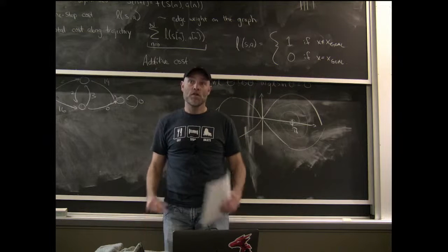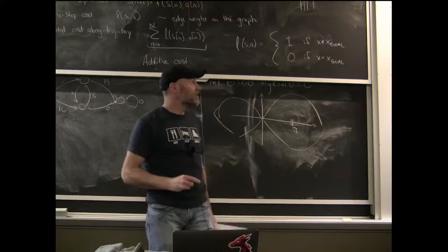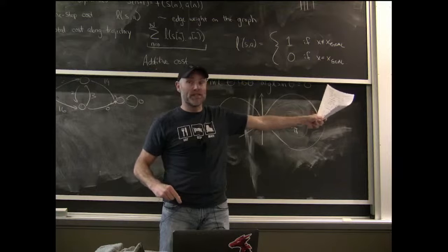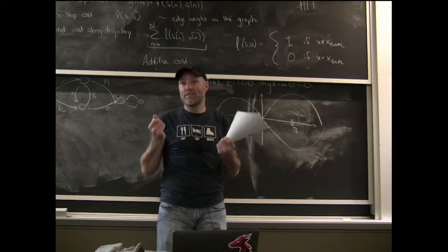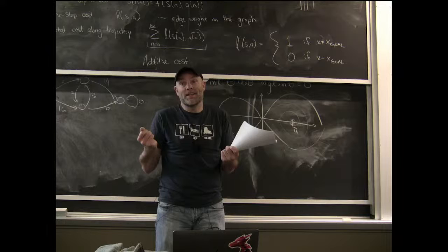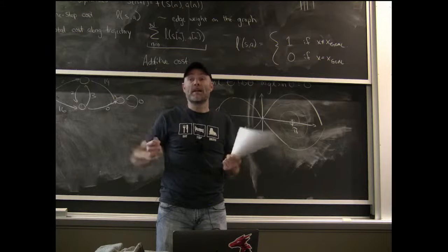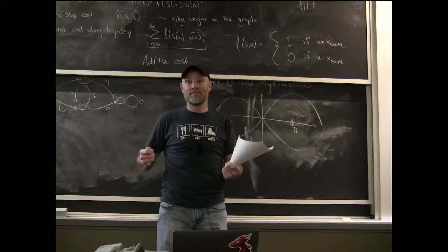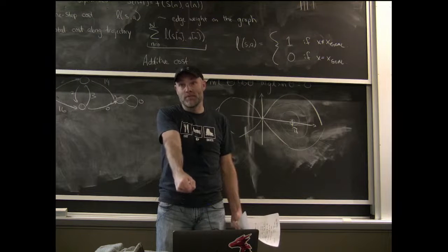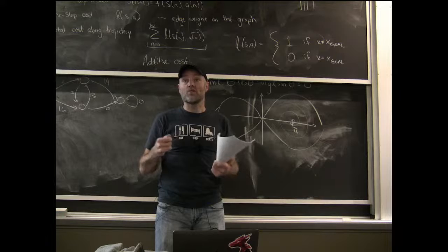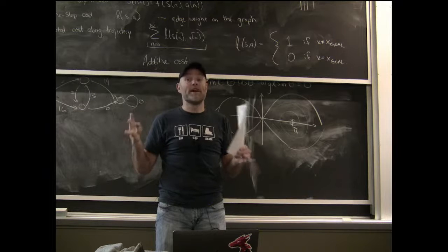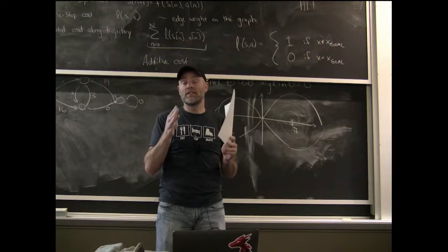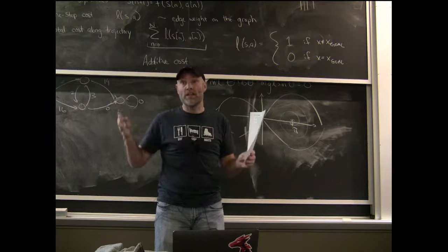There's like up, down, or so the minimum time problem for the double integrator, because we know that the optimal policy is bang-bang, we actually don't lose anything by only considering actions that are u equals 1 and u equals -1. Maybe u equals 0 if you want to stop at the goal. So that's a case where even though the mechanical system has continuous actions, considering control actions that are only discrete is okay.